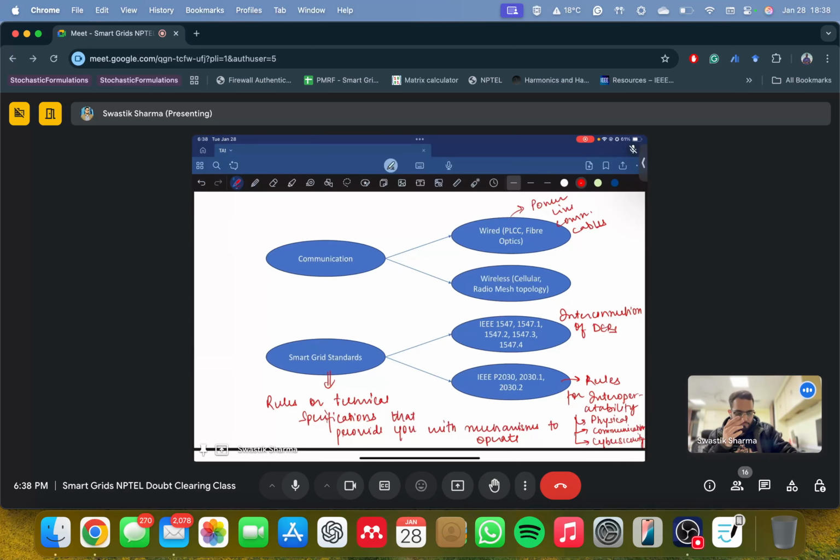Okay, so these two standards are very specific for your smart grid. It's just a review class. You must have covered this in the class itself when you went through the video lectures. But this is what they are used for. Basically, IEEE 1547 lays down ground principles that each DER interconnection must follow. For example, it specifies grounding approaches for your microgrids or your DERs where they are connected, so that they don't create voltages which exceed the rating of the grid, right?